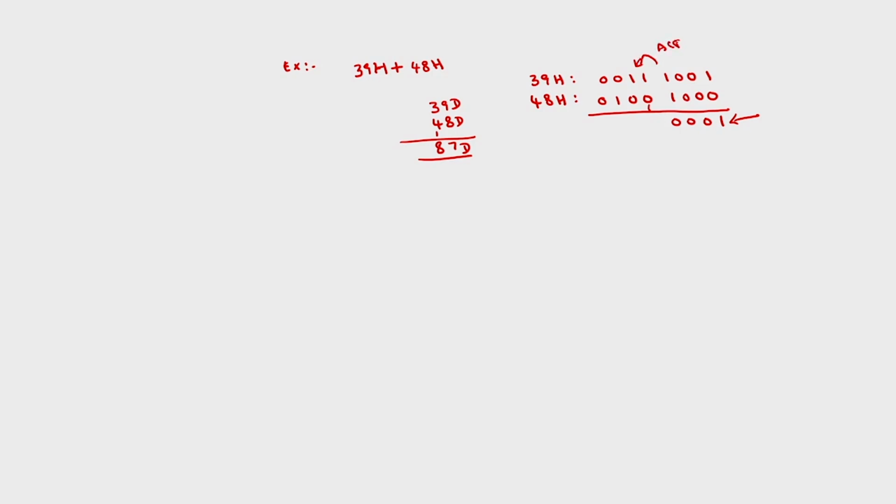So, auxiliary carry flag is set. Because of this, the instruction adds 6. In the upper nibble, this will be 1 plus 0 plus 1 is 10. Neither of these conditions is satisfied. This magnitude is 8, which is less than 9, and there is no carry flag, the carry flag is reset. So, this instruction simply adds 0000.